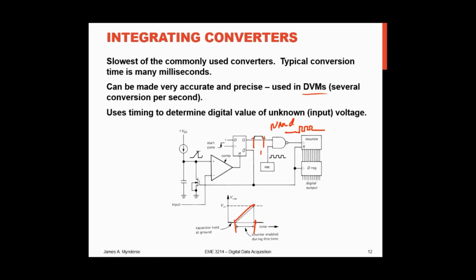So if I count the number of pulses during each of these conversion things, given the number of pulses, that tells me the time, and knowing the characteristics of the capacitor and the current that I've been supplying, I can convert that to a digital number and send that to our computer. And those are the basic technologies. There's nothing magic.